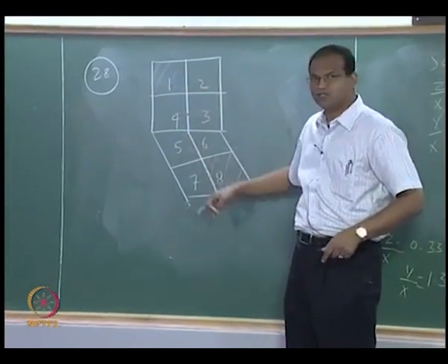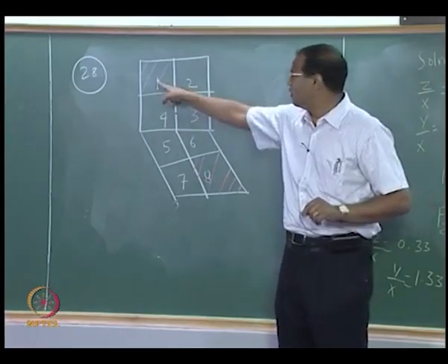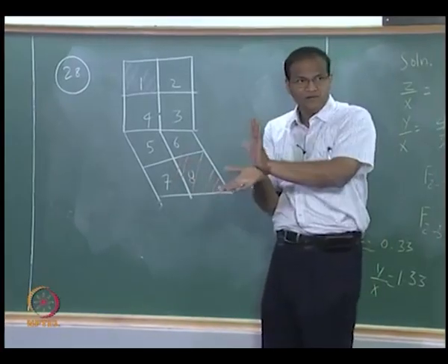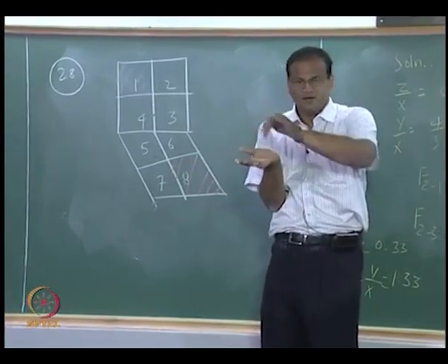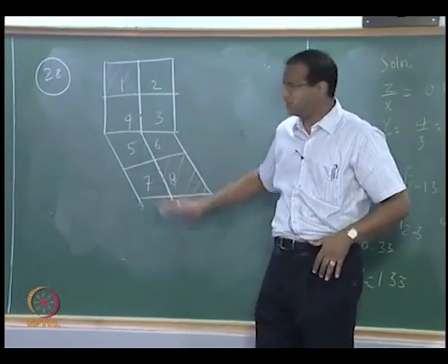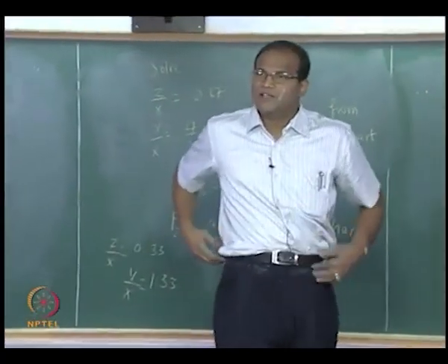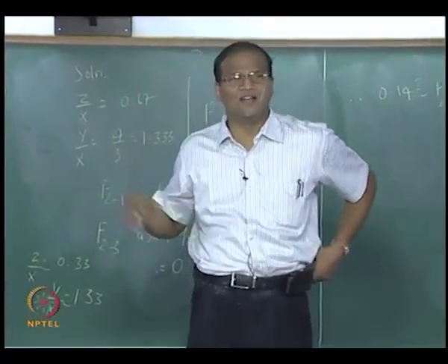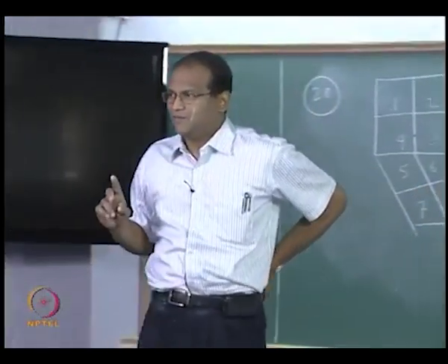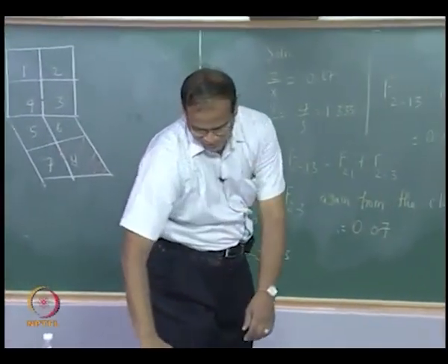Then some fundas you have to use, Vikram, you have to watch this carefully. F1 to 8 is same as F2 to 7, that is called the law of corresponding corners. F1 to 8 is the same as F2 to 7, okay, if it is properly oriented. And then depending on the size and all that, you can use your common sense and break down the complexity. And this of course is, I think Professor SPV's book on heat transfer, I think he has derived. We can also derive it from first principle, but it will be a long story.